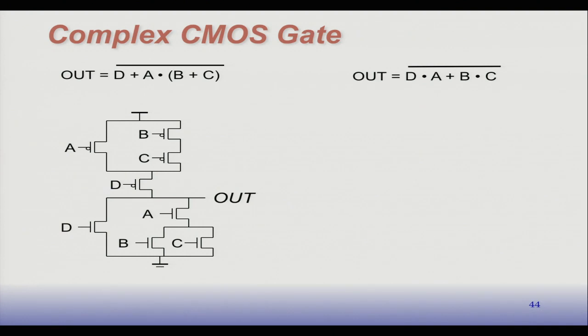So let's just try. I'm going to try this one here. Look at this network. The way you do this is we're going to make a simple graph where the edges of the graph will represent the transistors, and we'll use dots to represent the nodes. Remember, an electrical node is a place where components come together. So there's an electrical node for the output here, and there's an electrical node for the ground connection here. And then we have an intermediate node there, so we're going to put another one here. And then we'll put the arcs, which represent the transistors.